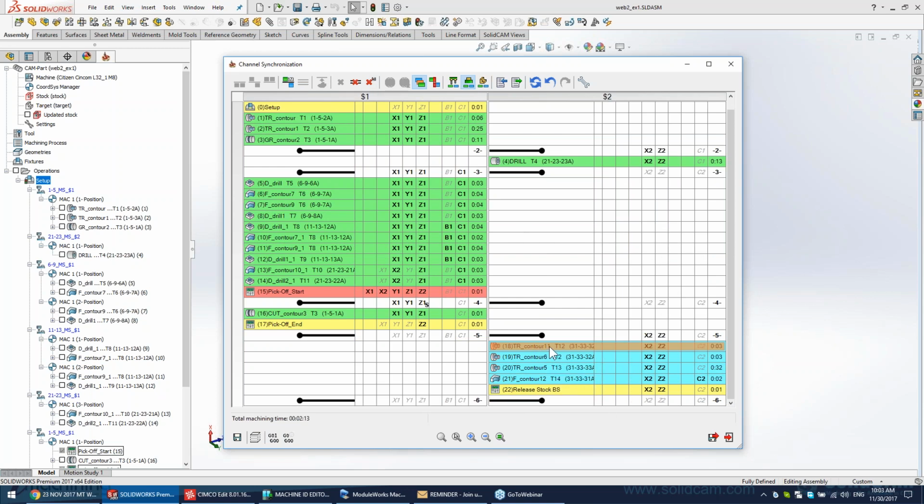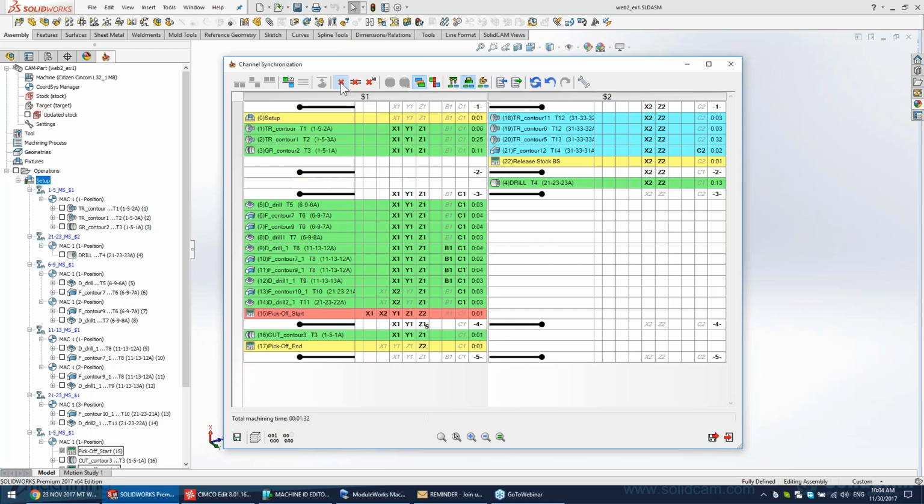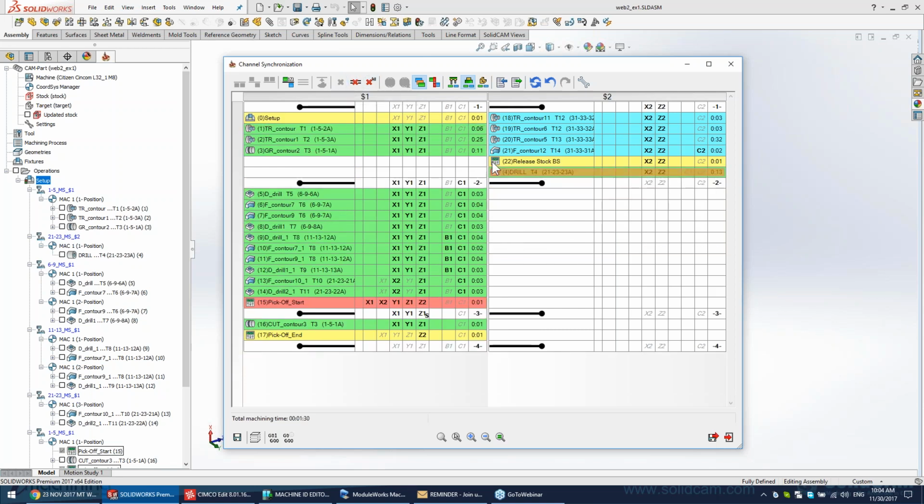we start to add the workpiece on sub spindle after all operations on main spindle. Add a new workpiece, and I will delete this label. I will delete also this label. In order to automate the process and to show you an example of superimposition, I will synchronize the grooving operation with the drilling operation together.